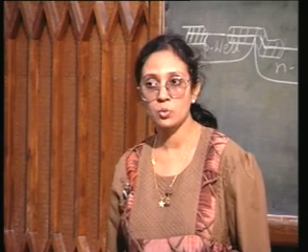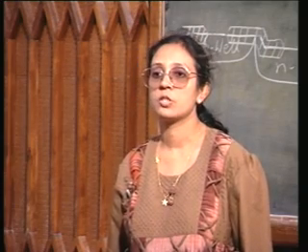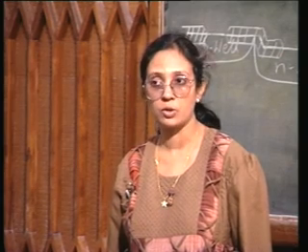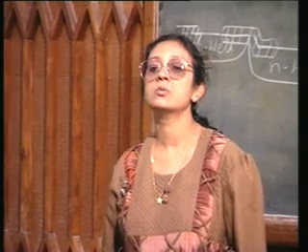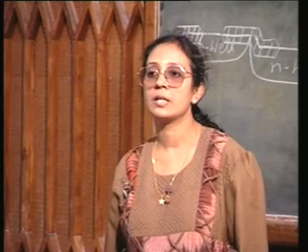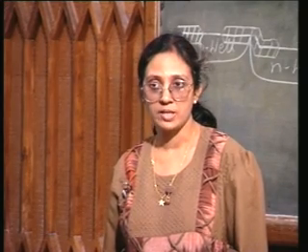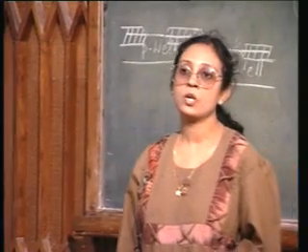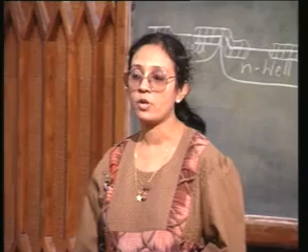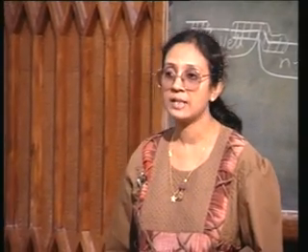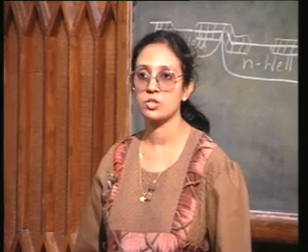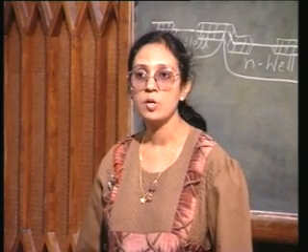So, this is one way in which CMOS technology is coming close to bipolar junction transistor technology, and which is in fact utilized when one is making the bi-CMOS devices. So, we will talk about the retrograde wells with epitaxy for CMOS in the next class, and then we will see how from there we can realize a bipolar junction transistor in the same process flow.